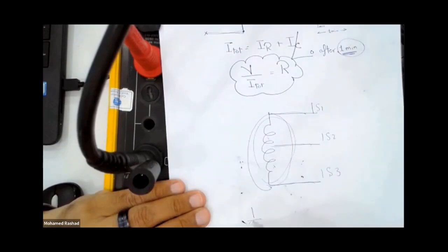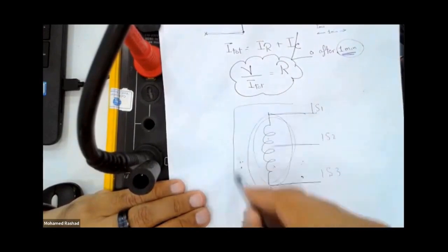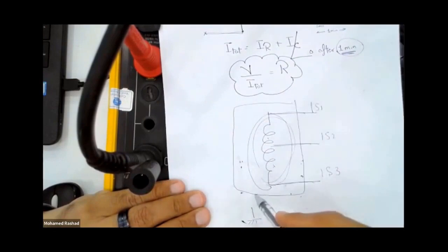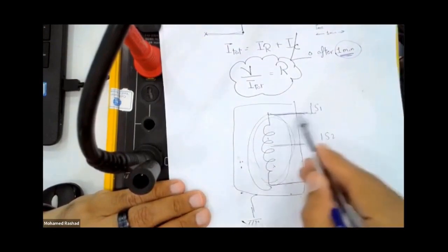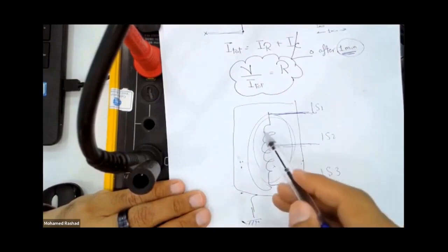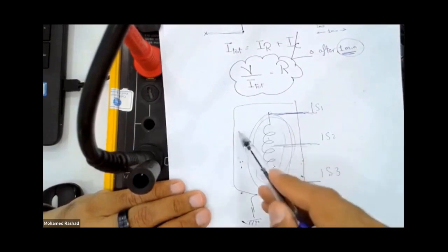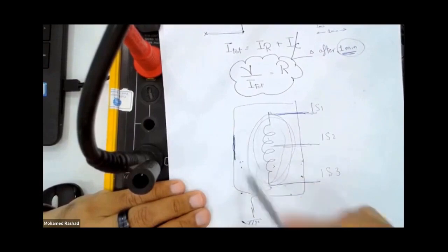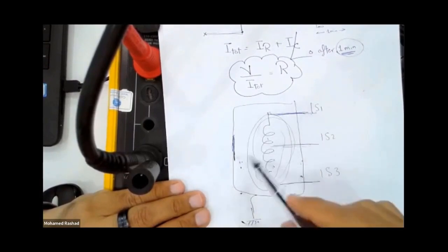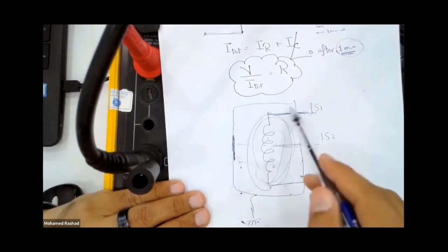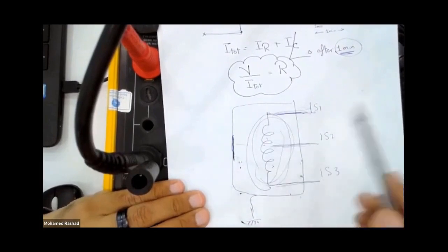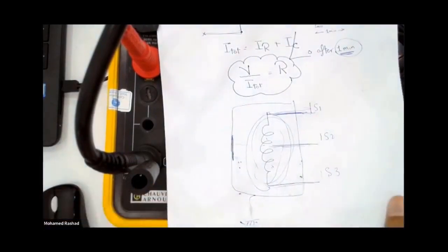This coil is supposed to be placed inside a casing. So this casing is supposed to be grounded in the end, right or wrong? So when I hold a terminal from any of these terminals, if there is any contact between the winding and the body of my set, it means there is a breakdown, whether I measure from here or from here. It's exactly the same idea.